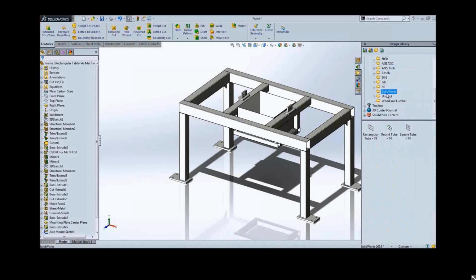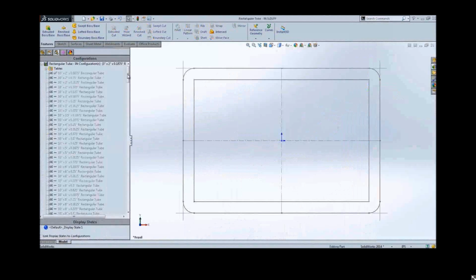So what SolidWorks has done is completely streamline this in 2014 with the introduction of configurable weldment profiles. Now each profile can be a configuration inside of a single part. If we open up one of these parts, I can show you what I mean. For instance, this square or rectangle tube could really be both because they're configurations. There are just a lot of different configurations underneath it.